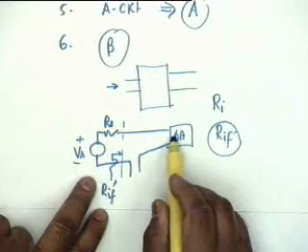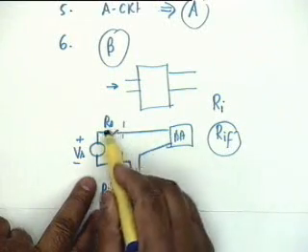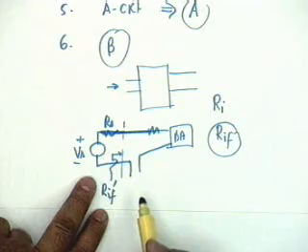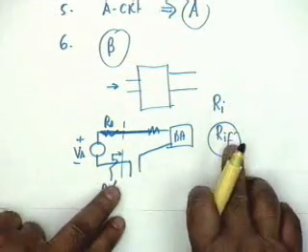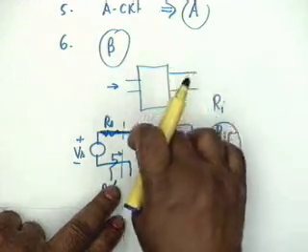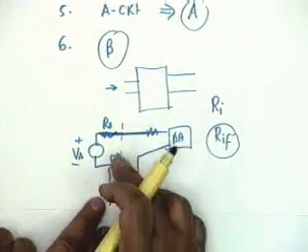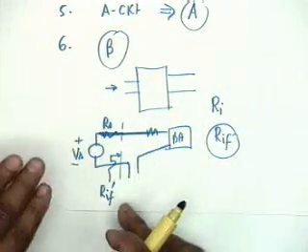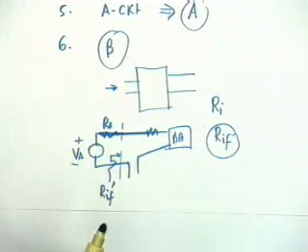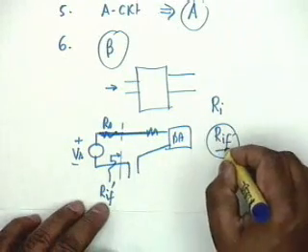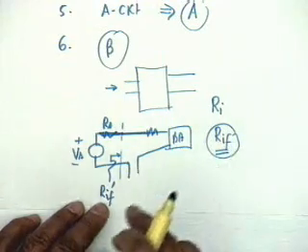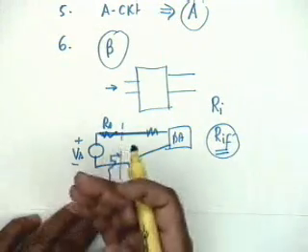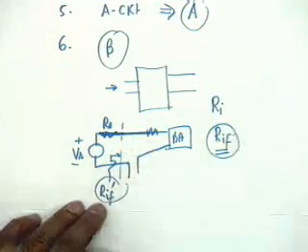The last point was that when you absorb Rs inside the basic amplifier, you have transferred this here to identify the A circuit, and therefore the Rif that you shall find out will include Rs. On the other hand, what I want to find out in the actual amplifier is what is faced by the source along with its internal impedance, and therefore the feedback input impedance will be different from what you actually want, and one has to extract the desired quantity from what you have found out.